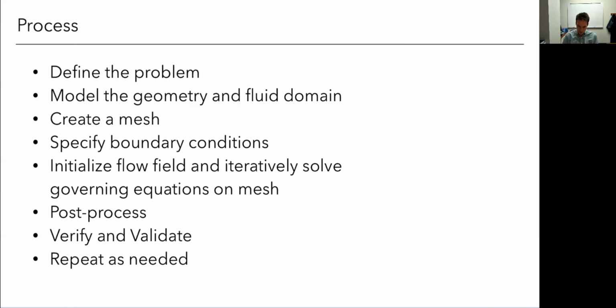Because if it's not, let's say this is my geometry, like I'm actually trying to model this fuselage that comes in like this, but it's so coarse that when I zoom in on the points it looks like this. Then no matter how small I make my fluid mesh, with these tiny cells here, I'm still going to be capturing this faceted geometry. So no matter how good I do that, I'm not going to make it more accurate. So I need it to look really smooth here. I need a very highly defined geometry.